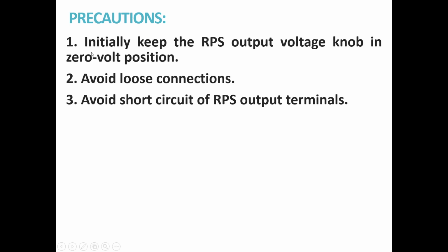Next, precautions. Initially keep the regulated power supply output voltage knob in 0 volt position. Avoid loose connections and avoid short circuit of RPS output terminals. You can pause the video and note down the precautions.